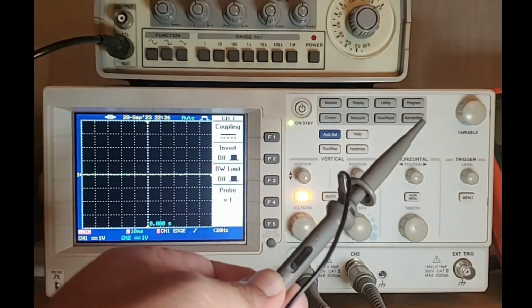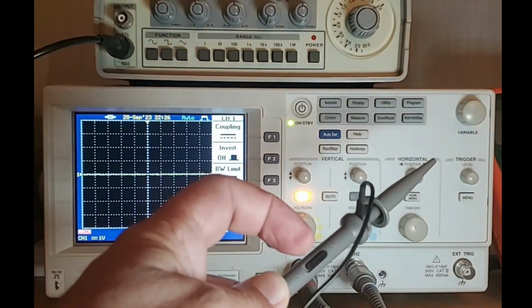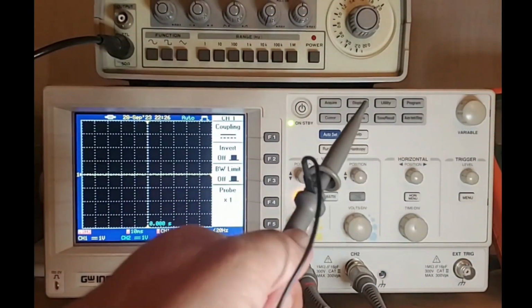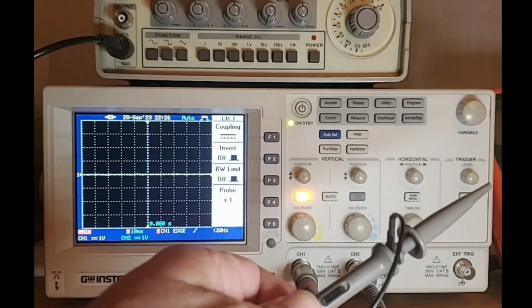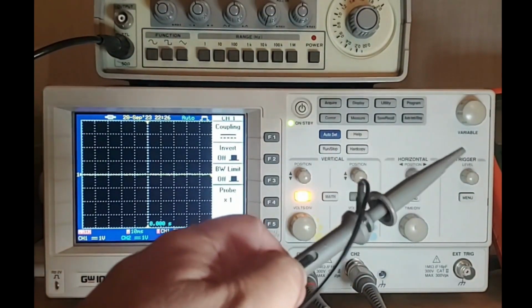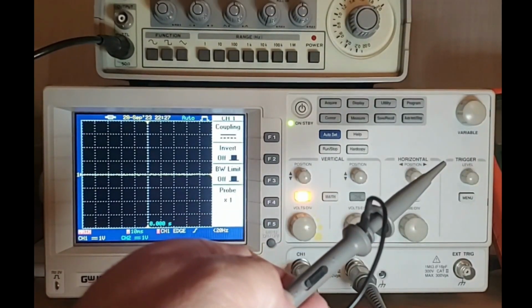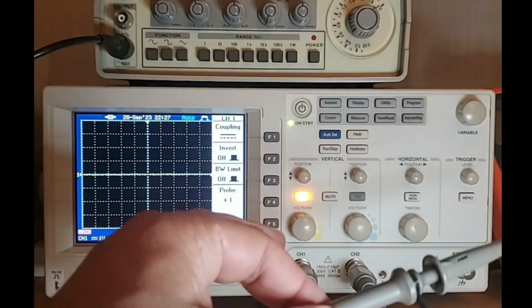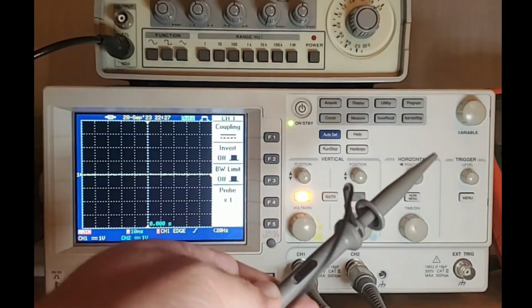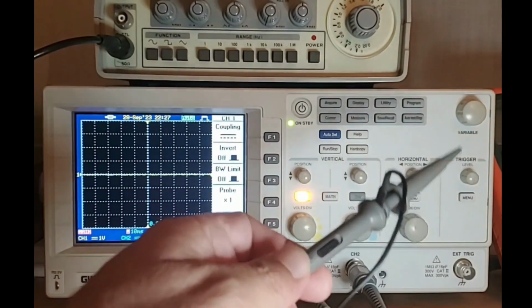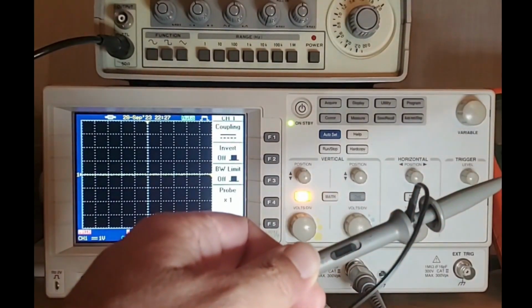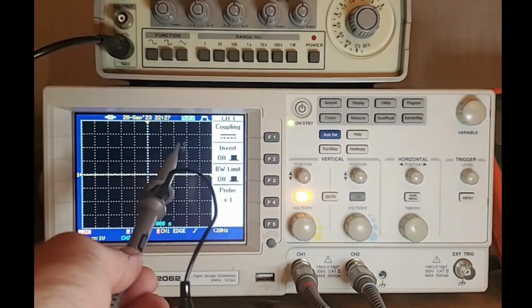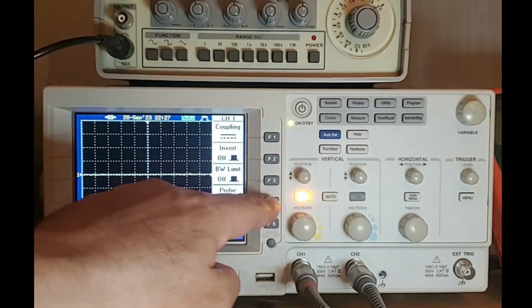Now, the probe here, most of the probes have this switch over here, which says multiply by 1 or multiply by 10. So you can change the position of the switch, and this is used to measure high voltages. So currently I'm using it at multiply by 1, so x1. So this means whatever the voltage is, the probe will just measure that voltage the way it is without multiplying by anything. But if I use the multiply by 10, then what the probe will do is that it will divide the voltage by a factor of 10 and show me on the screen. So then when I'm reading that voltage, I will multiply that by 10 over here.